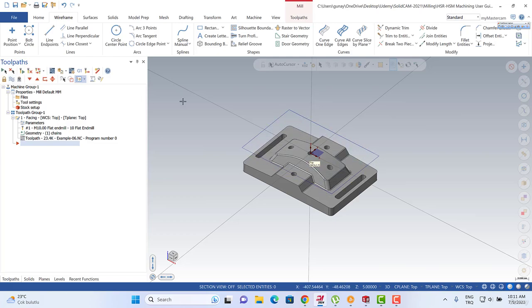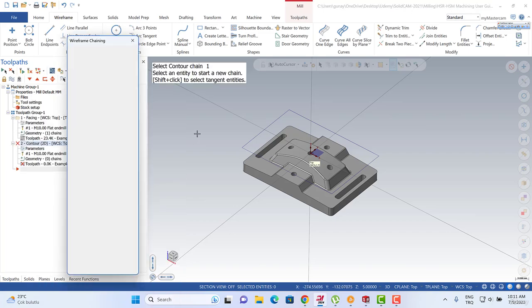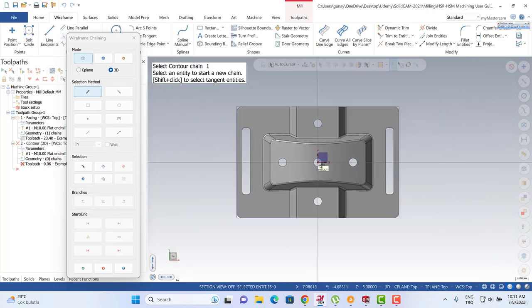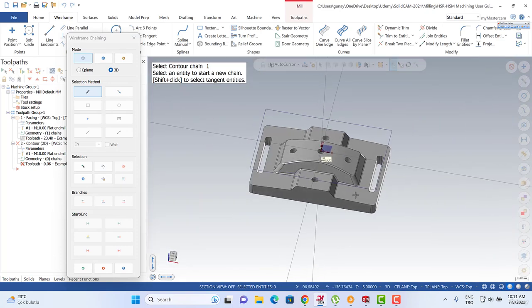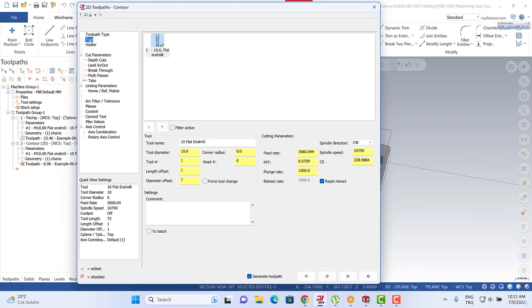It's also possible to create your contour toolpath. Okay, let me do that. And here I'm going to turn back to the contour toolpath. I'm going to turn back to top view. Okay, let me start with this line. This is also going to help us see our lead in and lead out process when we turn to the CNC section. This is going to be my tool.